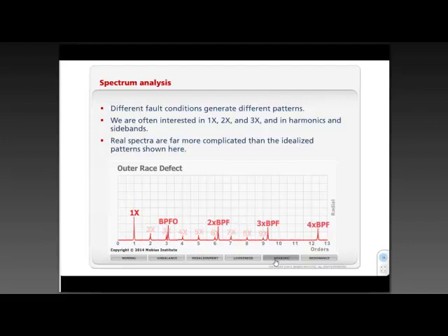It's not nice smooth vibration, so in addition to the one peak related to the bearing problem, and we'll talk about that more in just a second actually, there's harmonics. So that's what I'm expecting. And I'm expecting that peak not to be an exact multiple of 1x. So you can see it's 3.1x. It's very common to see a non-integer multiple. And with resonance, I might still see the 1x peak go up, but the resonance is amplifying it.